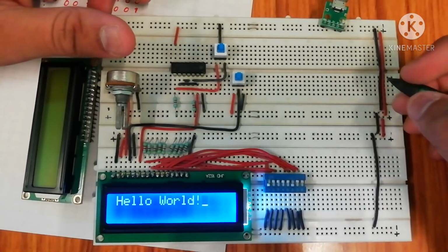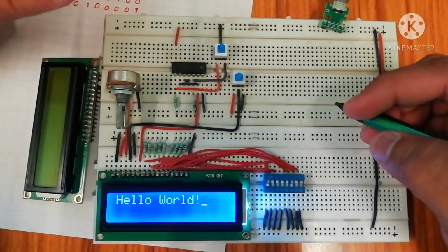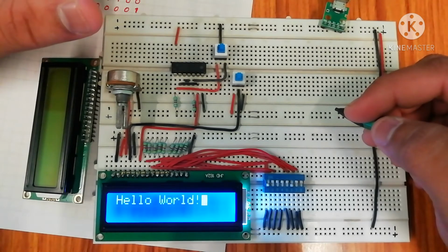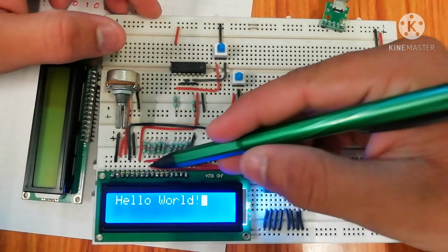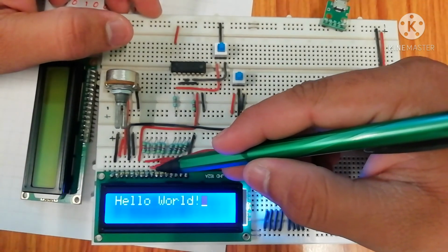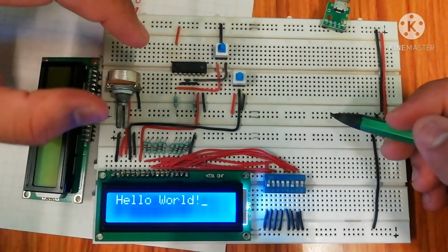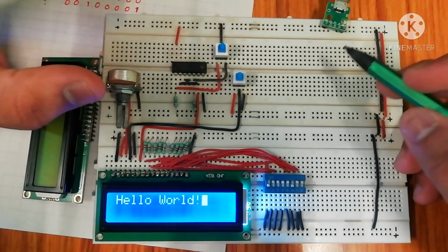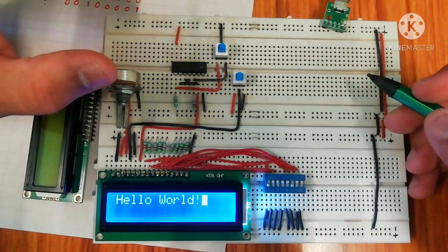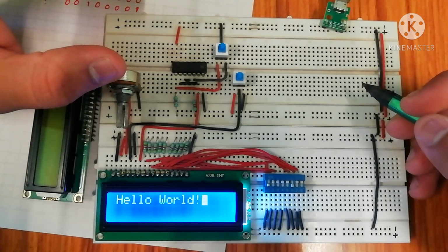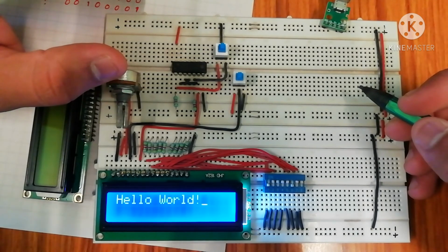Now, after watching this video, I hope that you have developed a basic idea of how these LCDs work and how a microcontroller / microprocessor uses them to display data. For example, the 8 data bits can be sent by a port on a microcontroller / microprocessor, and other control signals can be controlled by another port. In this video, I just covered how to write data on the display, but it can also be configured to read data from the display. Of course, there are many more features offered by these LCD displays, such as displaying custom characters, manipulating text left or right, scrolling right or left, and so on, but they are a topic for another video.